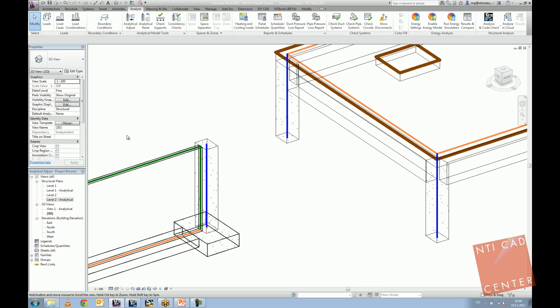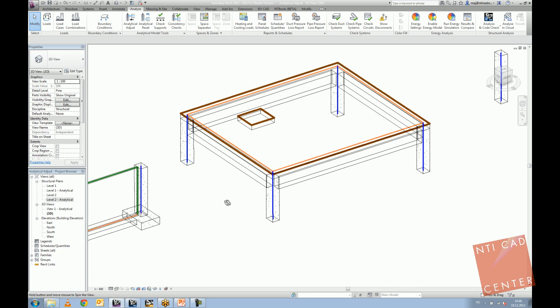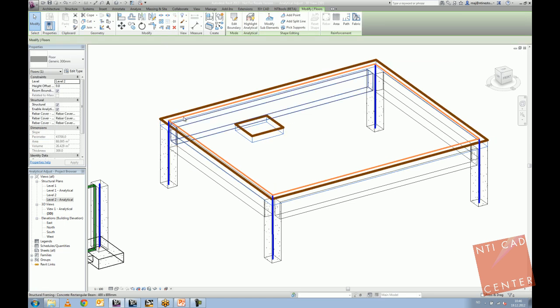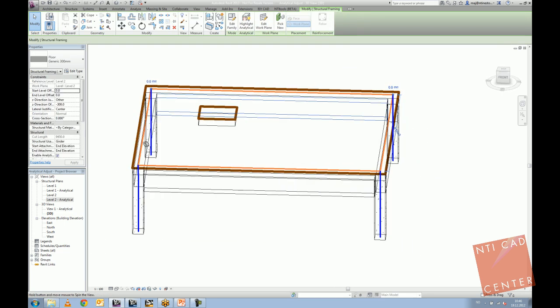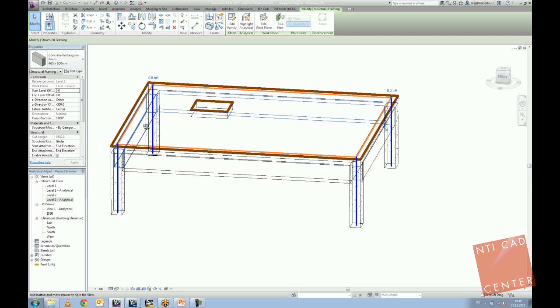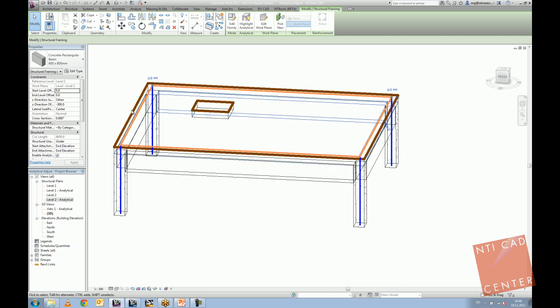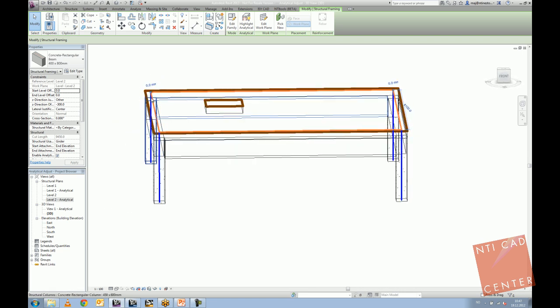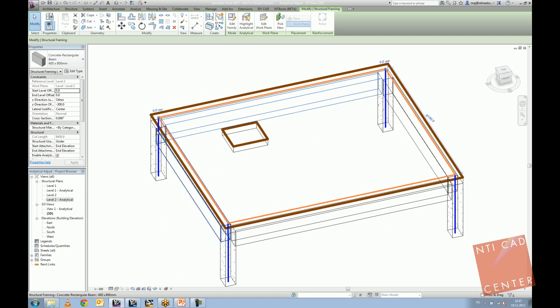So getting back to our elements. This is again something which is quite a common situation when you have your slab and when you have your beams, and basically you will have some kind of a distance here. It depends always on this distance, but sometimes it might be that actually the distance will be very small and the finite element mesh will be very dense here. So in that case, this is something you want to avoid, because you will have huge finite elements here and then very dense here, so there will be problems when meshing the whole structure.